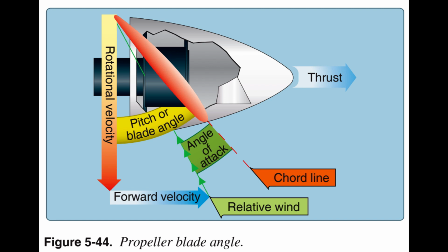Lift versus drag curves, which are drawn for propellers as well as wings, indicate that the most efficient AOA is small, varying from +2 degrees to +4 degrees. The actual blade angle necessary to maintain this small AOA varies with the forward speed of the aircraft. Fixed-pitch and ground-adjustable propellers are designed for best efficiency at one rotation and forward speed. They are designed for a given aircraft and engine combination. A propeller may be used that provides the maximum efficiency for takeoff, climb, cruise, or high-speed flight. Any change in these conditions results in lowering the efficiency of both the propeller and the engine.